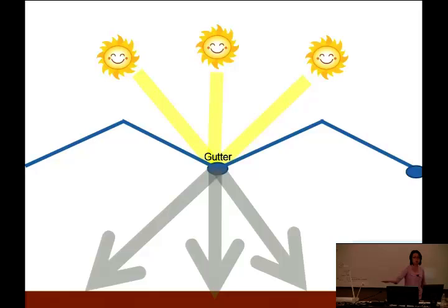And then if the shadow is moving, that's fine, because it's only temporary, right? So the plants can accumulate light on average. That's why we are talking about DLI rather than just instantaneous light. So if the shadow is moving, that's fine. But if the shadow is relatively staying in one location, that's the problem, because that particular location is going to be a low yielding location. So growers need to figure out how to manage that situation, or the greenhouse needs to be designed so as to minimize shadow in a greenhouse.